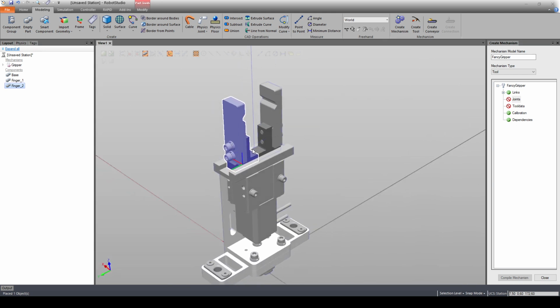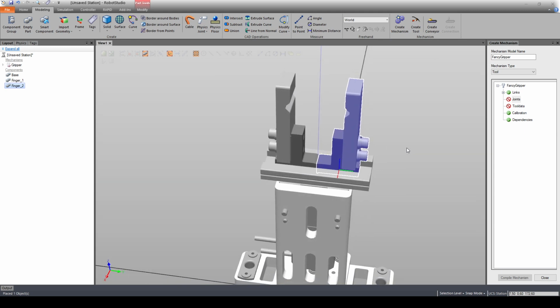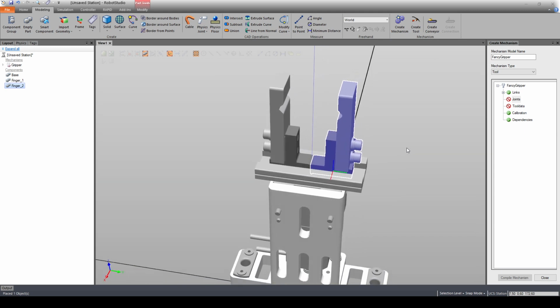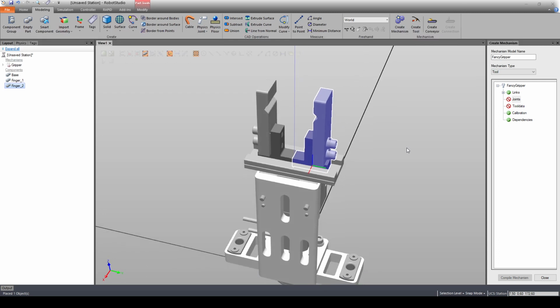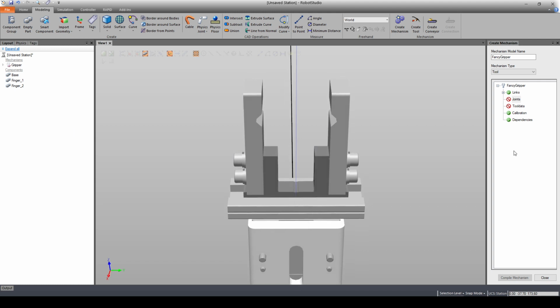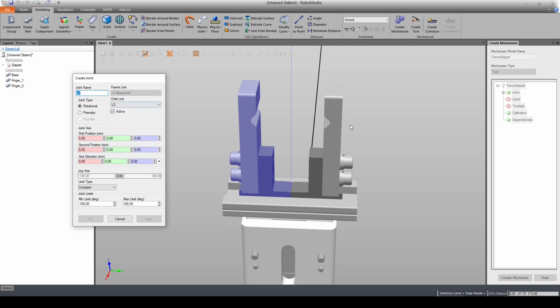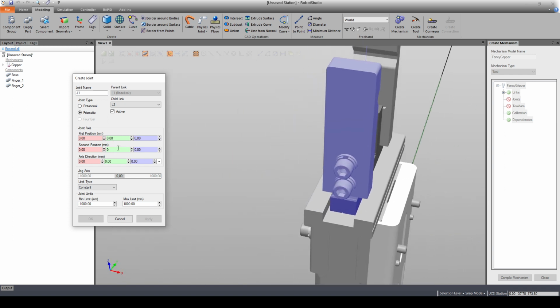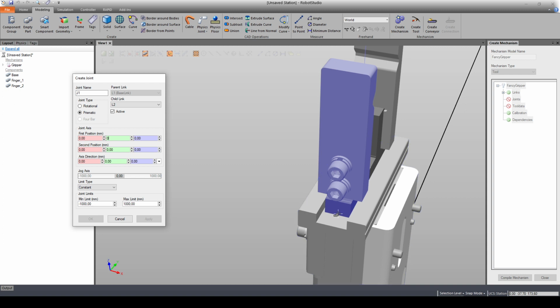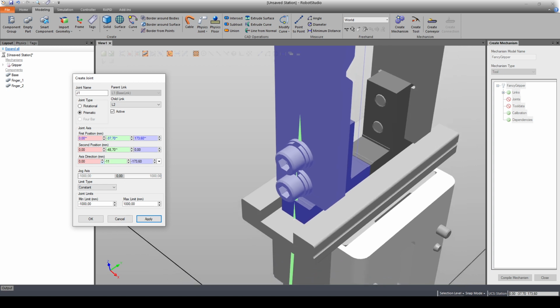And now I don't know if maybe they're not symmetrical in some way, but I guess you can adapt your mechanism so it fits your purposes. So from this spot we want to create the movement of these fingers, right? So we select prismatic joint, and we would like to, let's select this position here, and we want it to move -11.